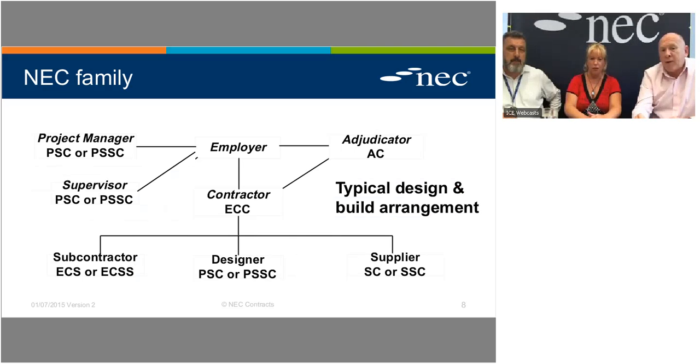The last model is a typical D&B arrangement, where this time the designer is an arm of the contractor. So now the contractor has single point design and build responsibility as far as the employer is concerned. The contractor, if he has in-house design expertise, could carry that out himself. If he externalises that, he would again use perhaps the PSC or the PSSC to engage an outside firm to procure such design advice. So that's just a very quick run through of the different contracts that may be used to engage design. And for today's purposes, we are thinking of design in terms of an asset in the built environment.